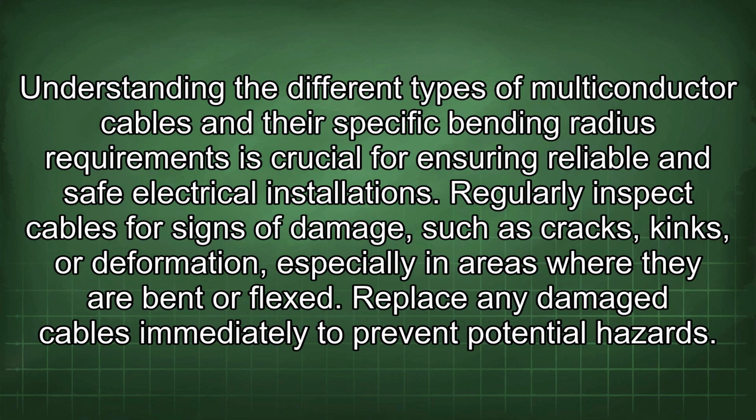Understanding the different types of multiconductor cables and their specific bending radius requirements is crucial for ensuring reliable and safe electrical installations. Regularly inspect cables for signs of damage, such as cracks, kinks, or deformation, especially in areas where they are bent or flexed. Replace any damaged cables immediately to prevent potential hazards.